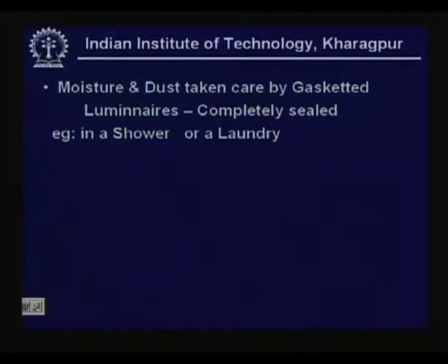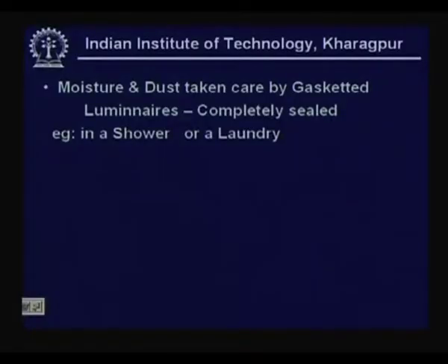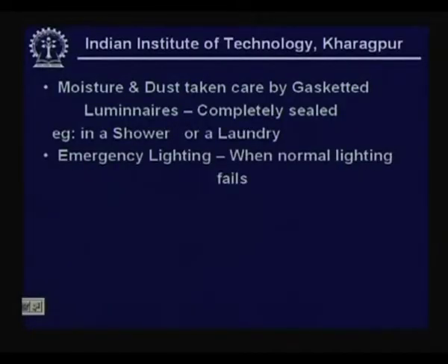Moisture and dust of course can be handled by having gaskets. See, a luminaire has a glass envelope through which the light is coming out. This should be gasketed. Inside the house one may have open luminaires with just fins. The other important area where one requires completely sealed luminaires is the shower or laundry where water is used.